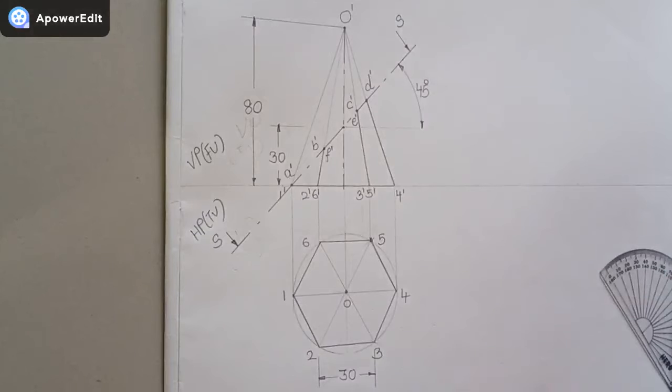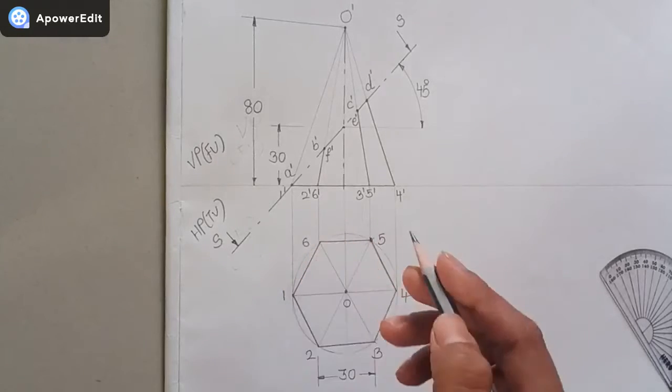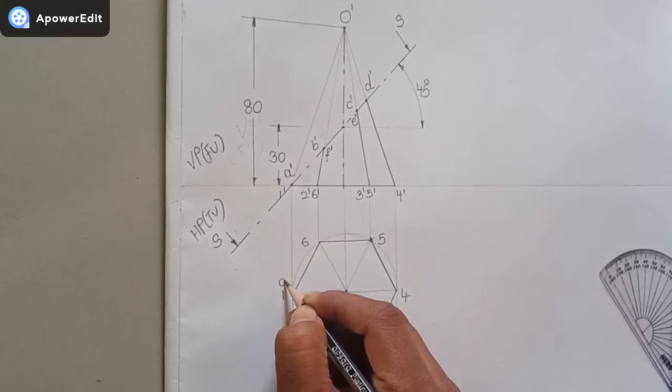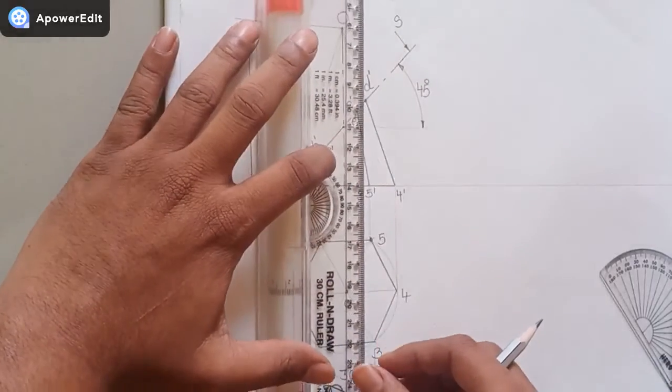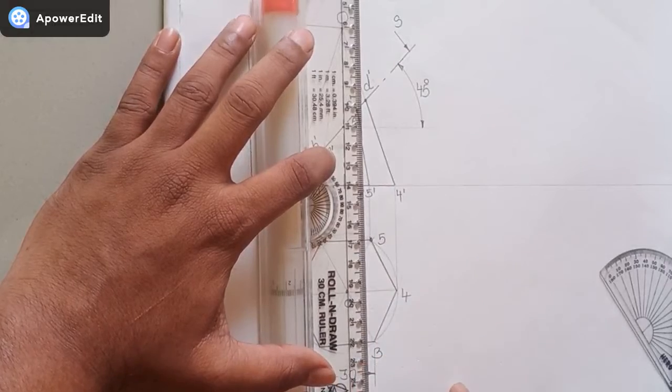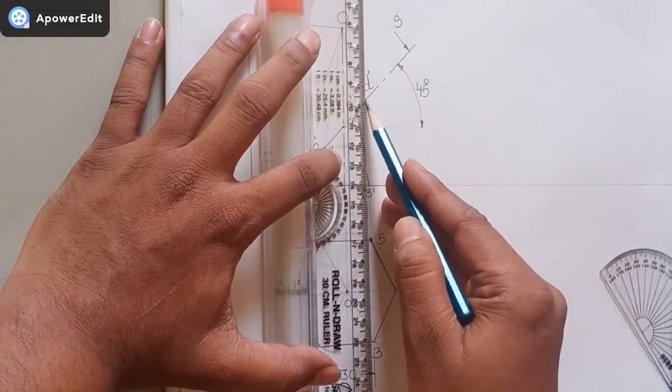Now our next point is to get the cutting section in the top view. So here one point you have to very clearly remember that O dash 1 dash and O dash 4 dash is the true length of the slant edge, which is O1 and O4 in the top view. So what we are going to do, we are going to directly project the A dash downwards to get the point A. Already one projection line is drawn, so I will directly write the point A on the overlapping at the point 1. But what about D dash point? I have to draw a vertical line from D dash point.